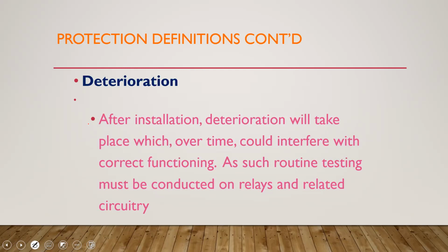Simple maintenance activities from time to time. I'm referring to it because since most of you would have been on campus at least once, you would have seen them washing insulators, washing the substation down at home. Of course, you had bird droppings and that sort of thing, but that in and of itself will impact the operation of the substation. So simple things like this.